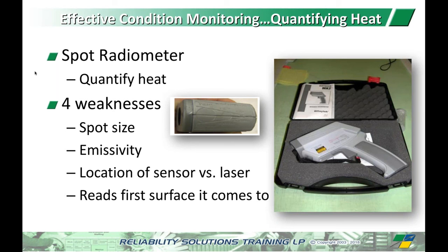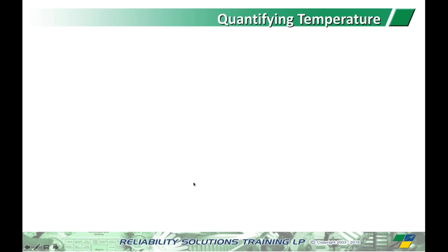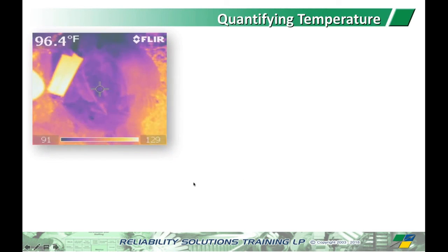And again, anytime we're dropping oil from high to low pressure and not doing effective work, then we're wasting heat. Oh, by the way, the energy to create that heat, you're paying for. So in terms of energy costs, not only are you causing reliability problems because you're overheating the machine, you're also paying to do that, which doesn't seem to make a lot of sense.